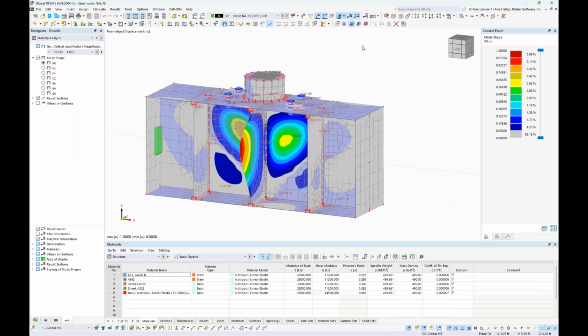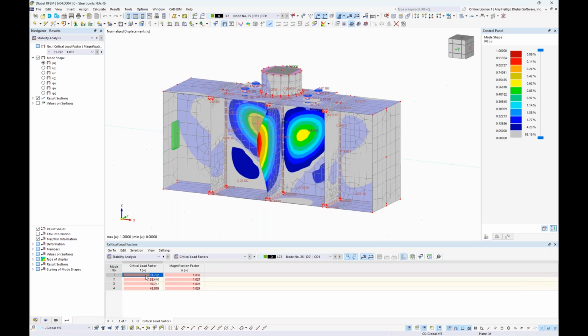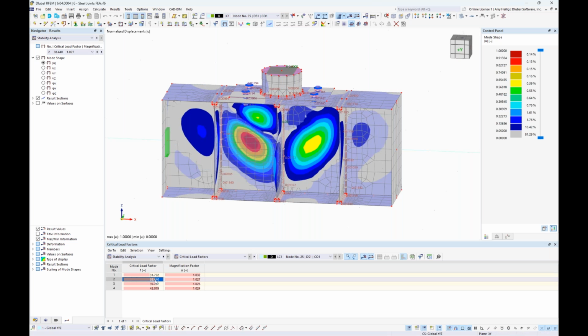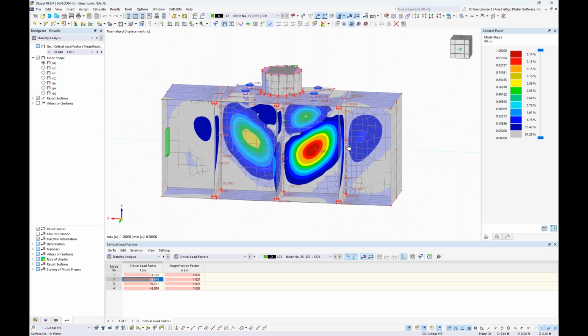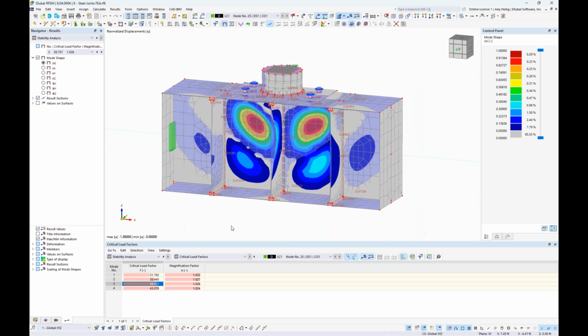So every example that we've seen up until now is the same workflow that's going on underneath the hood, where we can view here under the stability analysis results 4 different eigenmodes, the critical load factor of 31.729 before we see kind of the buckling of that stiffener plate, and then also the relevant mode shapes here with slightly higher critical load factors. So again, we start to see concern for the buckling of these web elements. So pretty unique and powerful, again, about what's going on underneath the hood for any connection type because of the ability to generate this FEA.